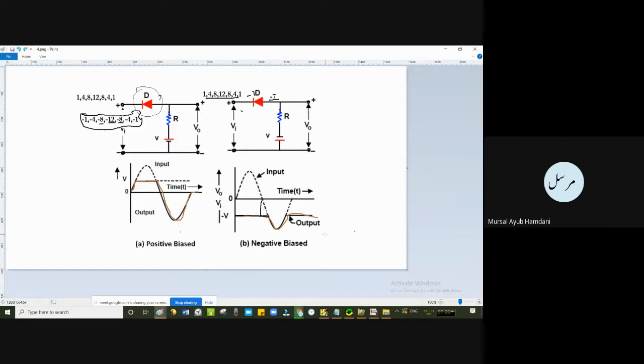Okay. So accordingly, only when the value is greater than or equal to -7 in magnitude, the diode will be forward biased, and then accordingly we will follow the input for this amount of time on the curve. And then when again it makes a value shift to be less than -7 on the negative side of the diode, we follow this.